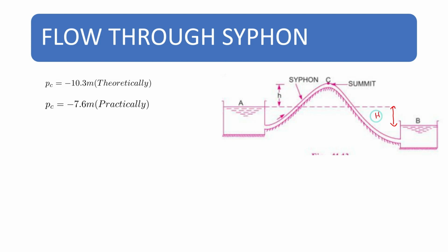h, so the head loss, you can write this as h is equal to, because at the entrance to the pipe there will be a loss that is equal to 0.5 v square by 2g, plus 4 FL v square by 2g due to the friction loss along the pipe, plus at the exit of this pipe you will have v square by 2g.